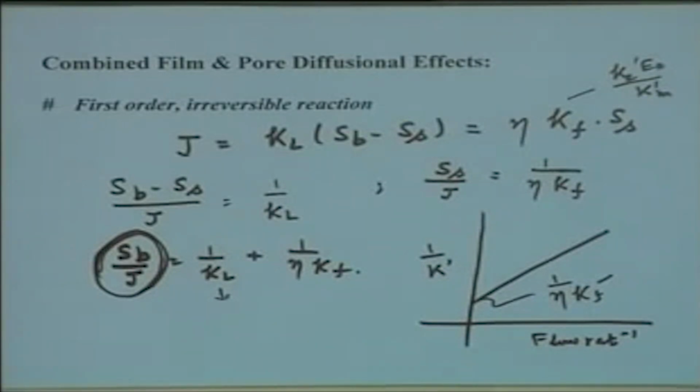You see, if you consider the reactor performance in terms of 0 order or first order kinetics, if you take any substrate concentration at the feed and carry out the substrate conversion to a very high level, you will have the overall reactor performance which is much closer to first order kinetics. If the conversion level is not very high, then the reactor performance will be controlled by 0 order kinetics.